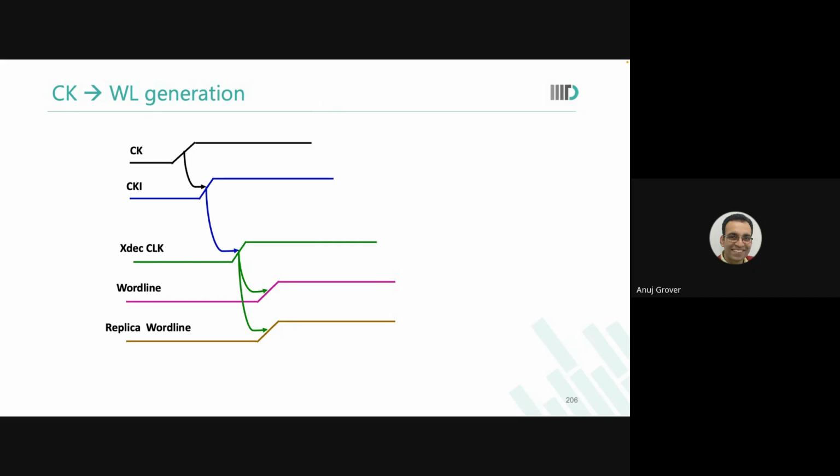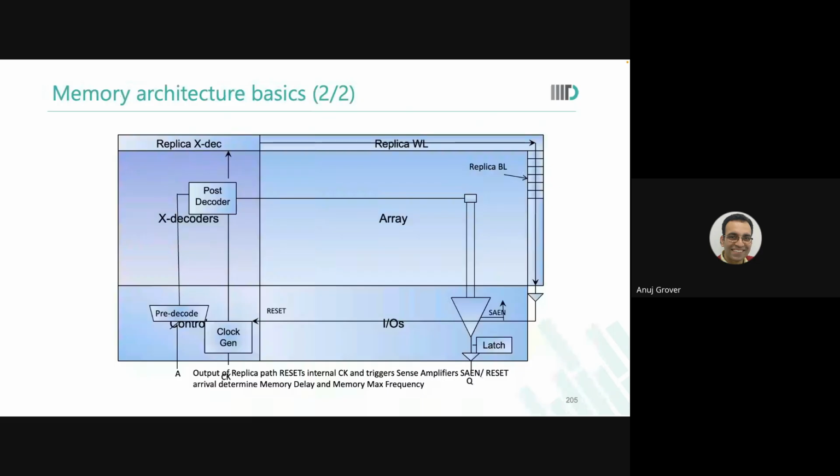Because let's go to the last slide once again. See, what did we see there? This particular sense amplifier or this particular inverter will get triggered after my worst case cell would have been triggered. Am I right? And I'm saying that when the first sense amplifier right next to this particular trigger signal is activated, it should also have sufficient differential at its inputs.